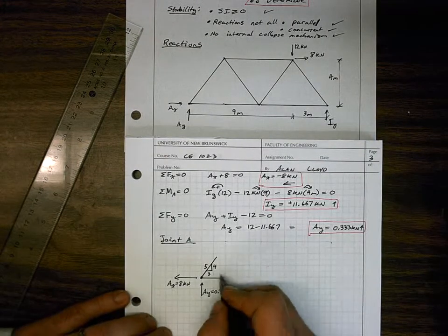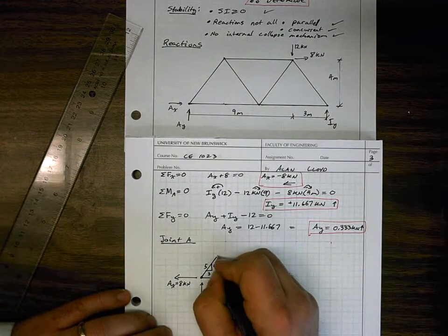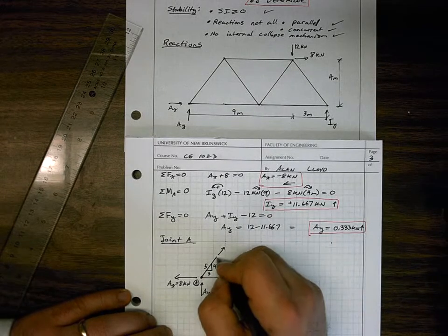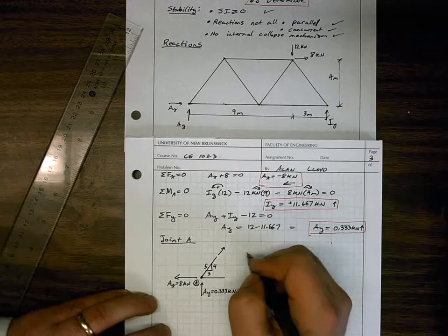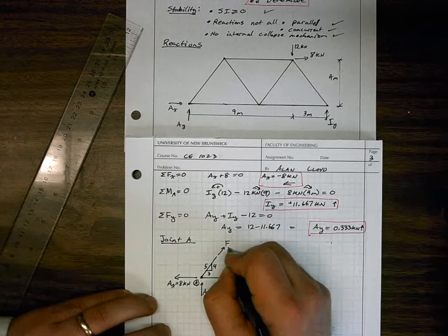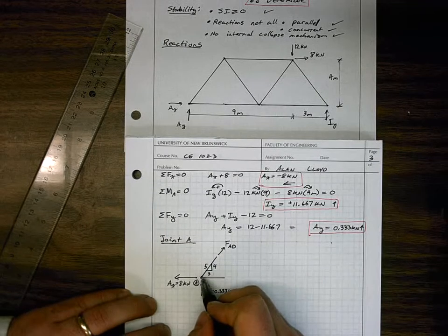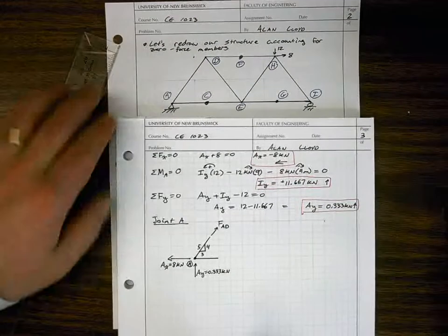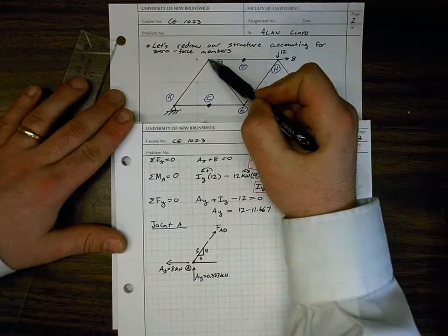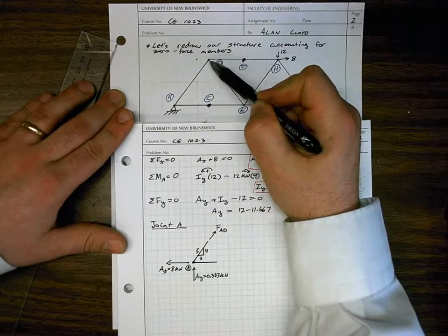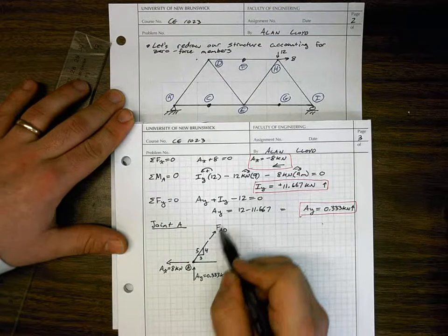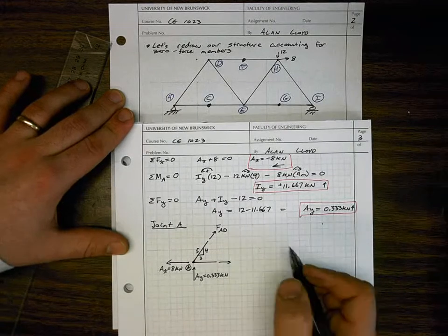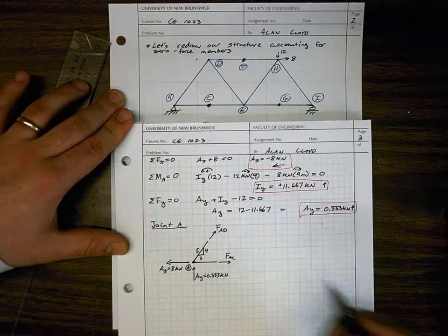Now that we have that established, we can say that we have an unknown. This is joint A down there. We have an unknown acting along the length of the member in positive local coordinates, meaning tension is positive, FAD, force in member AD. Here is joint D. So we're dealing with a force in member AD, and we label it with the joint that we're sitting on and the joint that we're looking at. So A is where we're sitting and D is where we're looking. And then since we don't know this value, this is FAD, we'll draw it as positive as well.